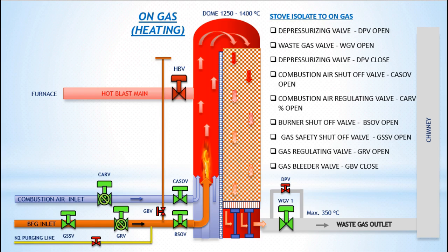Cooling cycle. Fuel and combustion air cutoff: the fuel and combustion air supply is cut off. Regenerator cooling: the regenerator cools down, releasing stored heat to the air blast. Air blast: the preheated air blast is directed to the blast furnace.